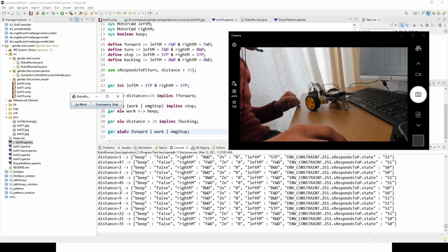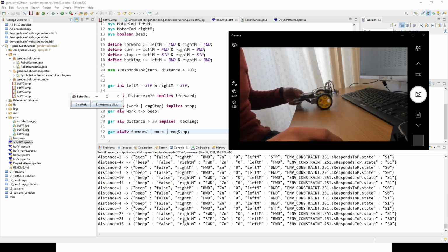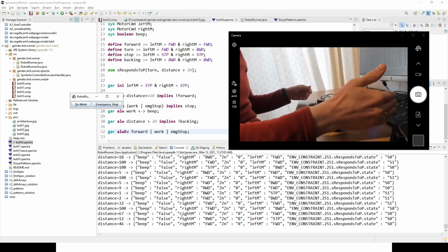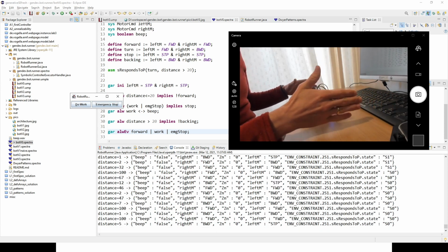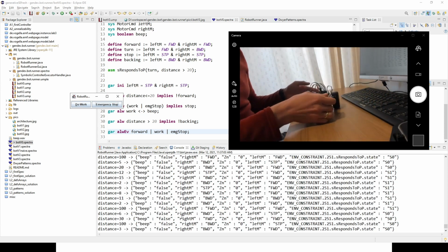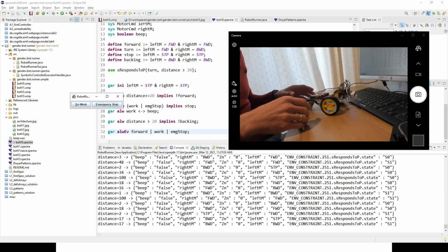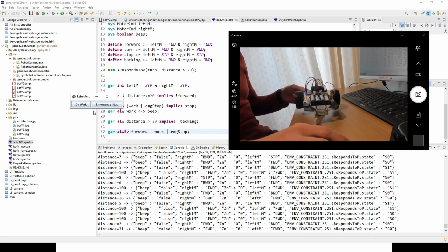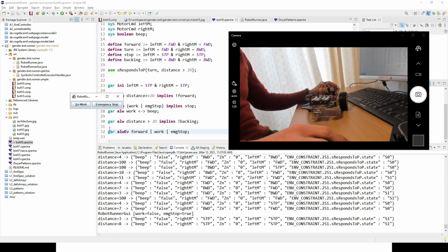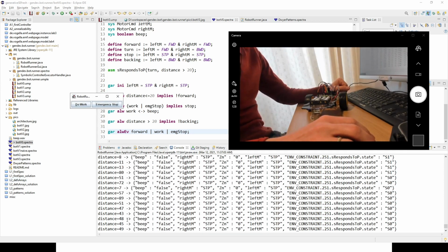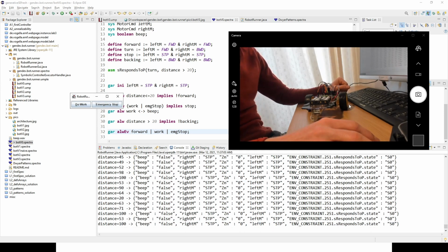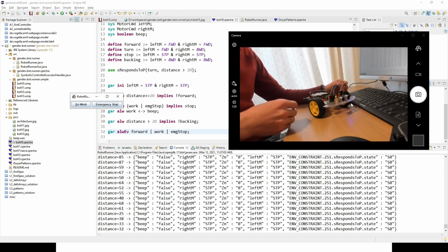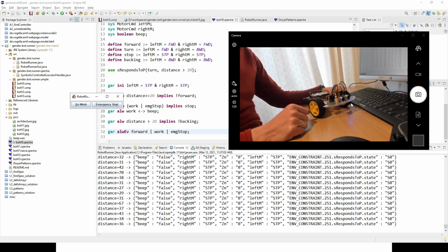So maybe there's something a little bit off with the sensor. Maybe also some delays in the network. I guess it's not really in these 50 milliseconds, but if the network is slowed down, then of course the messages will arrive at the robot a bit later. Okay, let's turn it off. Oh, no. Yeah, okay. So there is some slight delay. So maybe if you really want a better reaction time, you might want to put a Raspberry Pi on this robot or something like that, another small computer, or just make sure you have a fast Wi-Fi.